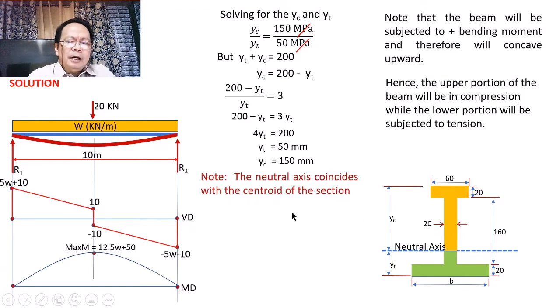So that, from our lesson in the determination of centroid, we say that a centroid can be taken by the use of the principle of moments, the moments of area, so that the moment of area about any axis being equal to the product of the total area multiplied by bar sub y, where bar sub y will be the location of the centroid from one reference axis, shall be equal to the summation of the product of the individual area multiplied by the location of the centroid of that area from the same reference axis.